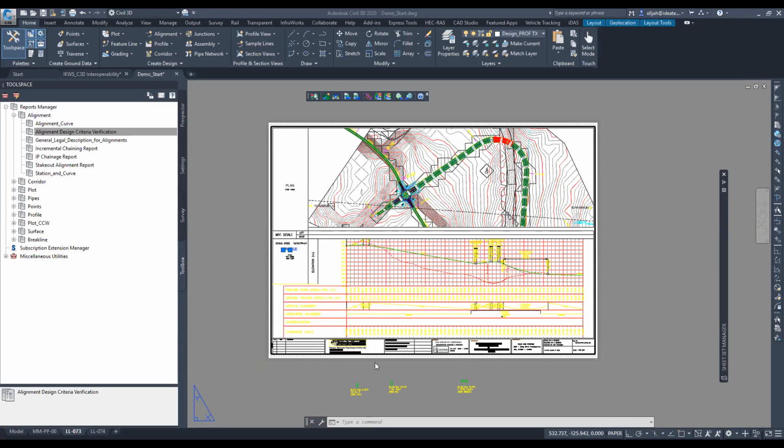Thank you. We have another question from Patushedzo. I think this question came about when you started doing the demo. Where do I get the background image that you are using? So for the background image, you can either use Civil 3D. If your data is georeferenced, you can use the freely available Bing map within Civil 3D, and that is if you georeference by setting the coordinate system for your model. But with InfraWorks, it is also freely available if you use Model Builder to build your model from scratch.